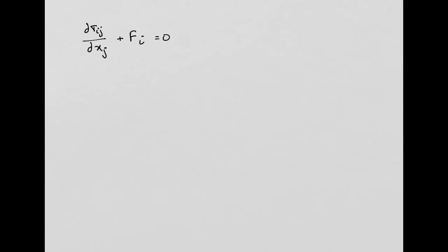We need to have 0 on the right hand side, and what is left on the left hand side is going to be my residual after I replace the variable I'm looking for, to solve the differential equation, by my approximated variable or approximated function, right? In this case, my goal is to get my stress field.